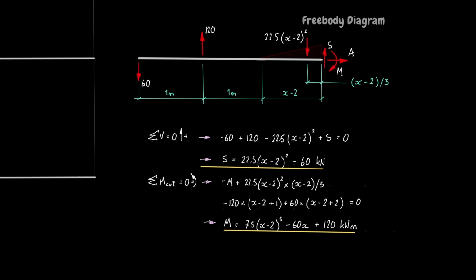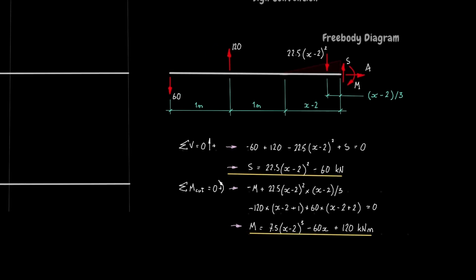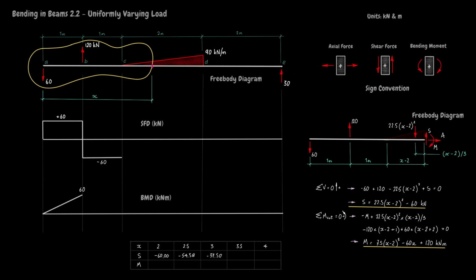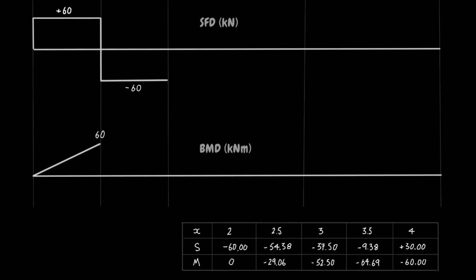As we are sketching the diagrams, values will only be calculated at half-meter intervals. Draw a table, then tabulate the shear and bending values using the equations on the right. Dr. Jim used Excel to get the results, as he does not trust himself with a calculator. Other software such as Google Charts, MathCAD or MATLAB can be used. MathCAD is a wonderful tool, and there's a free version. Dr. Jim is a big fan, but that's for another video.